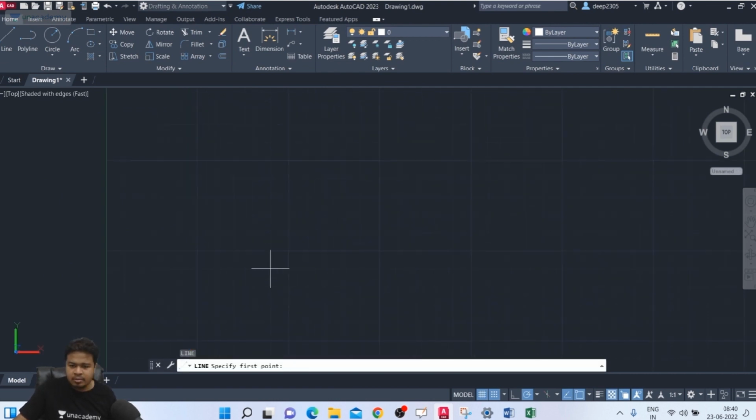If you observe your mouse, it is snapping at every 10 distance. This particular small box is of 10 distance. If you press F9 again, the snap is off and the cursor is moving very smoothly. It is not snapping at the intersection of the lines.